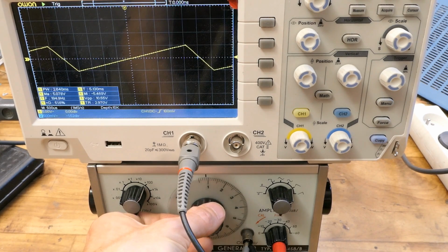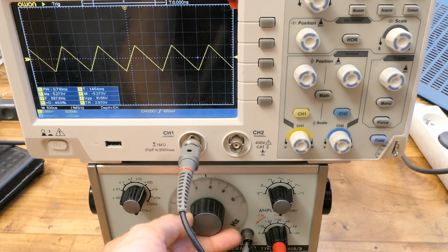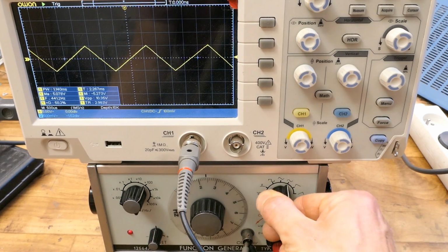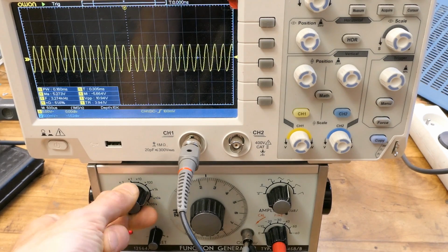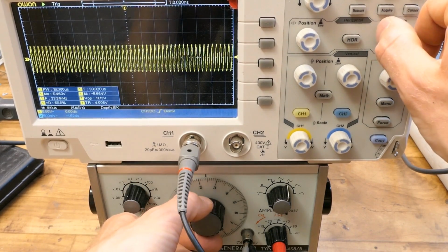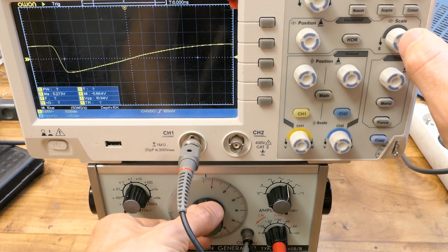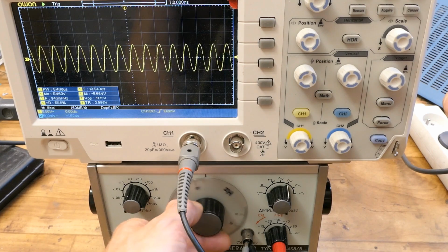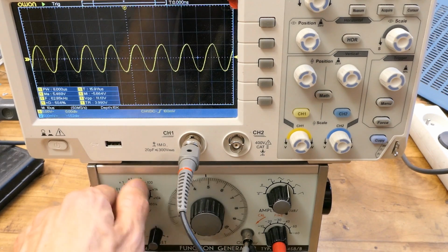And the problem always shows up in the lower half of this knob range. And this problem also seems to be completely frequency independent. This is happening the same in all positions of this switch. Again, in the lower part the sine wave is distorted, in the upper part not distorted.